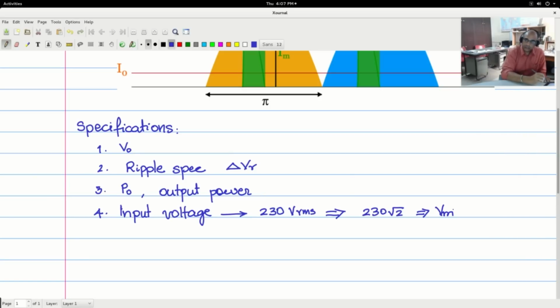But it is not just that. Your input voltage will swing from place to place, from 180 volts to 270 volts, so plus minus 20%, plus minus 30%. These kinds of swings you will find in a real mains grid. So you should also specify the input voltage tolerance.